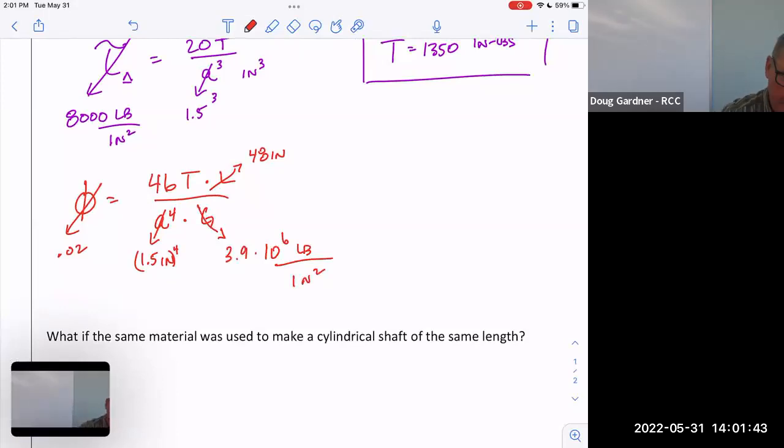And so torque then, let's see, I got pounds on the bottom. So I guess torque is going to be inch pounds again, since I got all these inches. So does that all work out to unitless again, like I did a minute ago? Let's see, I've got 2 inches there, gets rid of 2 inches here. Then I've got 2 inches on the top, 2 inches on the bottom. I got pounds on the top, pounds on the bottom. Sweet. Yeah, that's actually unitless, so that's going to work. Remember though, I got rid of the units, but that doesn't mean 1.5 is still not to the fourth power. The inches is not to the fourth power. It's gone, but that's still 1.5 to the fourth power.